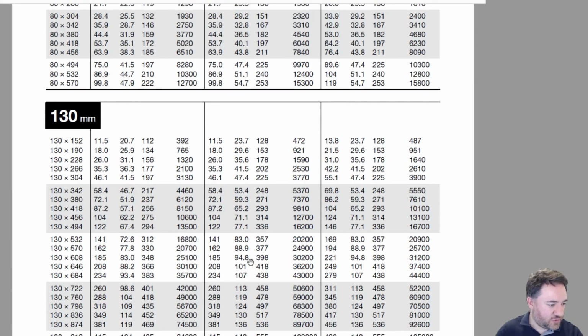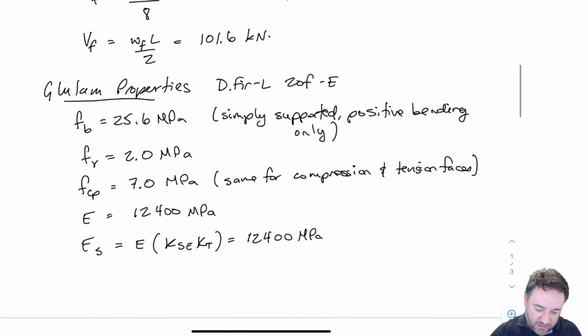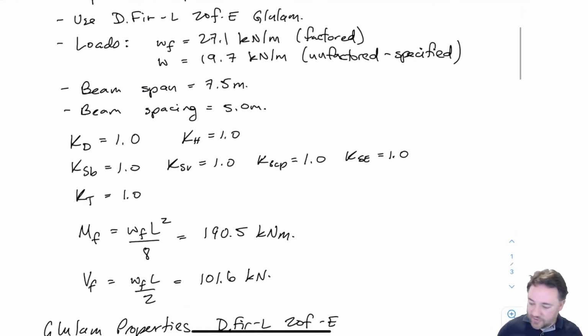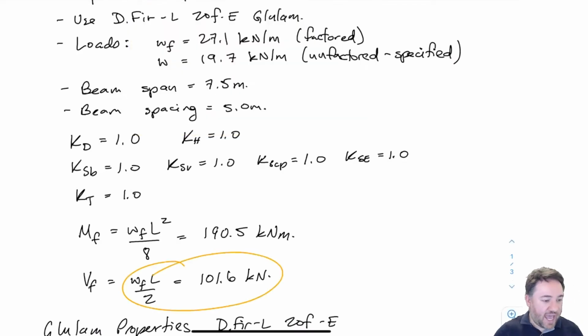Because I have some ways to juice this number a little bit, which we saw before. So this is the simplified shear calculation. I know that I have some options to get a higher effective shear resistance. For example, I can look at my VF at d from the support instead of looking at VF at the support. The VR here comes from our VF that we calculated, this wL over 2 value, that's the VF at the support. And remember that for longitudinal shear design, we can look at VF at d away from the support, which is going to reduce that number. So my true design number can actually be a little bit less.